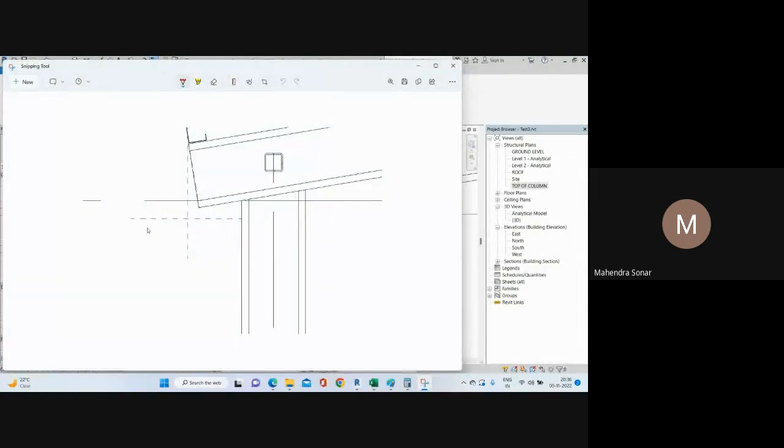Okay, so suppose I want to give the C purlin here, like that. And my plate comes here, like that. So in fabrication this plate is welded to the outside of this column, right? Then after that I want this gap to be 10 mm. Okay, and then the first bolt is at 35, it depends on your bolt diameter, and then 70 here, and then 35 here. Okay, 35.